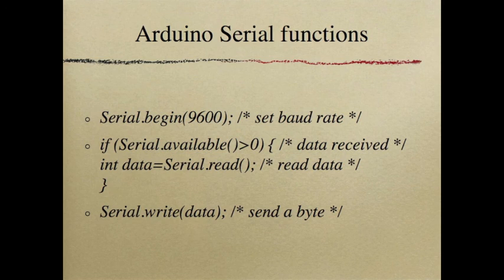Luckily, you don't have to do that counting of the period by yourself, because Arduino has provided tools and a library where you can just make a function call to set the baud rate and use the read or write function to send or receive data. A little note here: if you want to read data, make sure that you check the serial available function. If the result is more than 0, it means we have data waiting, or else you will read nothing from the serial line.